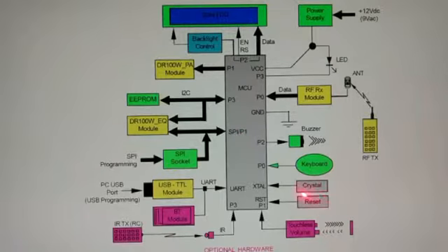This is basically an RC circuit. The Atmel 89S52 MCU requires an external reset. But for other MCUs, which are newly designed by STC, the reset is included internally, so the external reset is no longer needed.